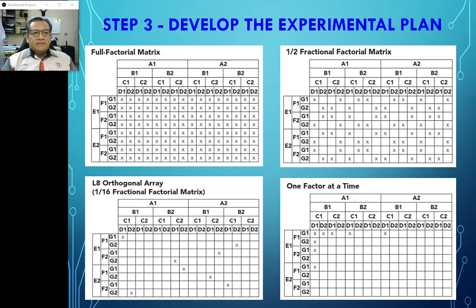Now, in step 3, you have to develop what kind of testing combination you want to make. Because design of experiment involves many types of tests, and each test is unique. You have to set different set points, different parameters, different noise types for each of the testing conditions, and only then could you achieve the best performance with less variation, or minimize the noise.